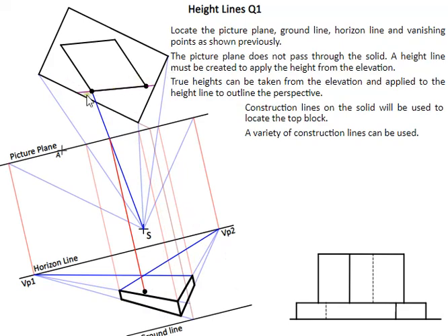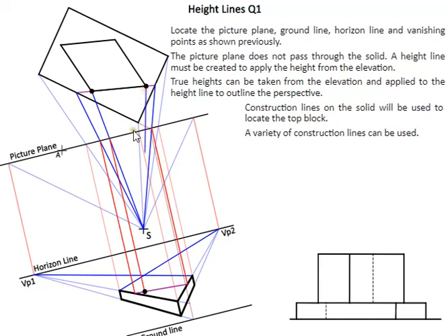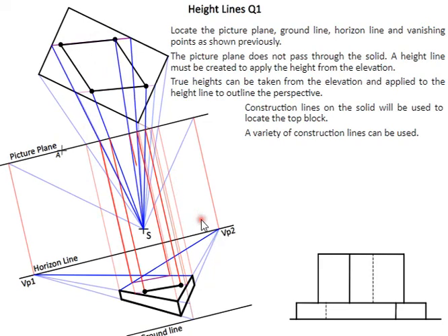Next we have to look at joining another point to find this point here. In this case, what we can do is bring this purple line onto the base here in plan, bring it to the picture plane, then bring it down, so this gives us this position here. Same on the other side, draw this line, then bring this point here to our spectator and mark it here. Now these two points can be drawn in heavy. Next, the back two points, similar method again, marking. So this is how we locate it.